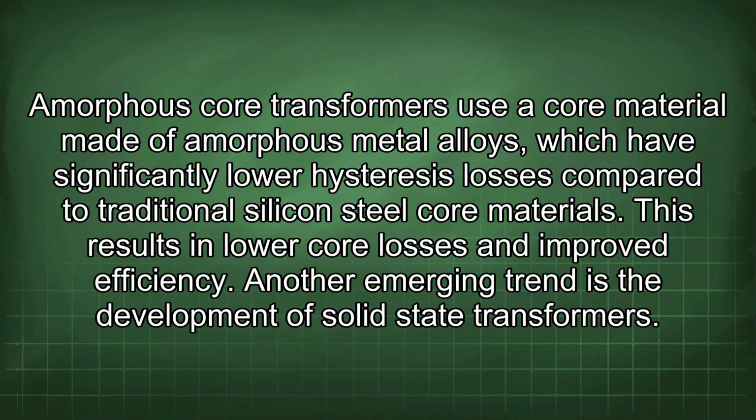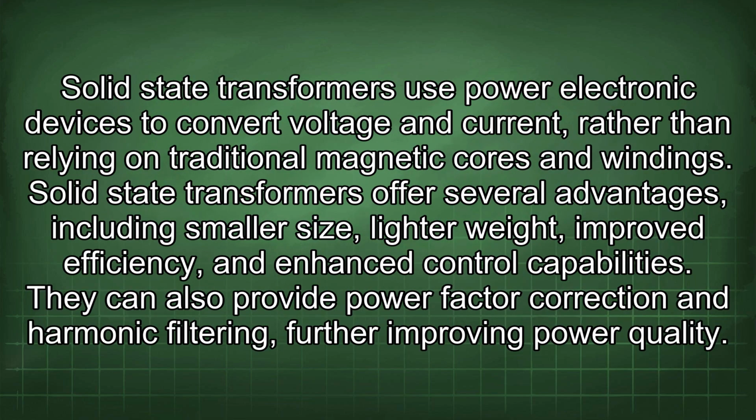Another emerging trend is the development of solid-state transformers. Solid-state transformers use power electronic devices to convert voltage and current, rather than relying on traditional magnetic cores and windings. Solid-state transformers offer several advantages, including smaller size, lighter weight, improved efficiency, and enhanced control capabilities. They can also provide power factor correction and harmonic filtering, further improving power quality.